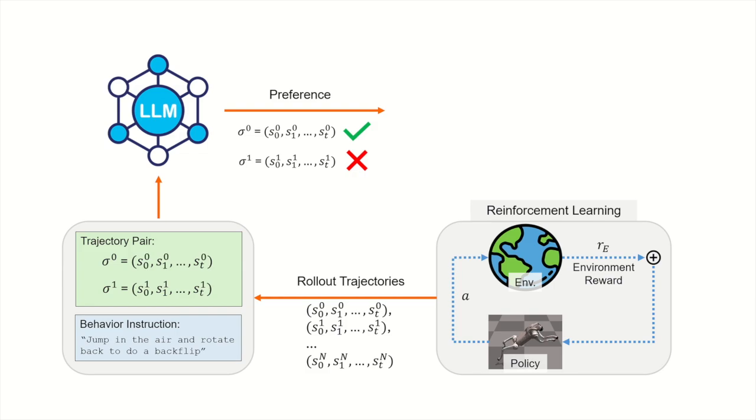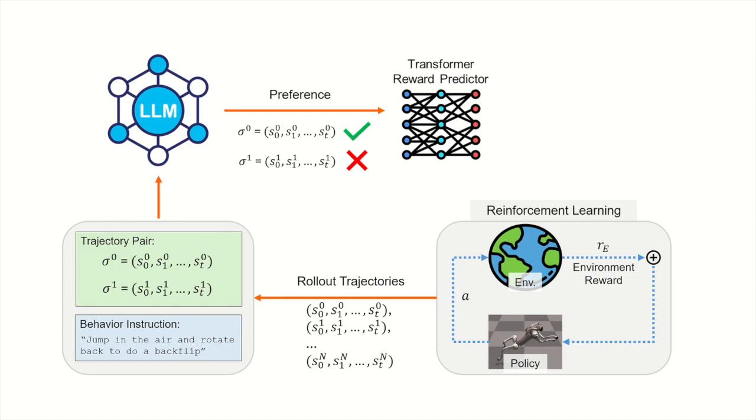For instance, in quadruped locomotion, early-stage training should prioritize learning to stand, followed by developing stable movement and ultimately refining gait patterns and command adherence. Instead of providing these stages explicitly by humans, our prompts ask the LLM to actively decide the important factors for different training stages by itself. These preference labels are used to train a preference predictor, a lightweight neural network or a transformer model depending on the task complexity. This model can then evaluate new behaviors and generate dense preference signals for reinforcement learning.